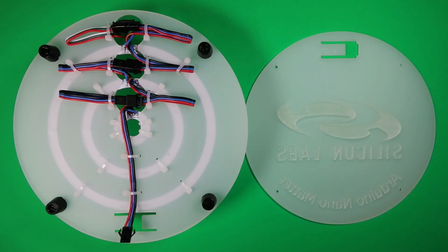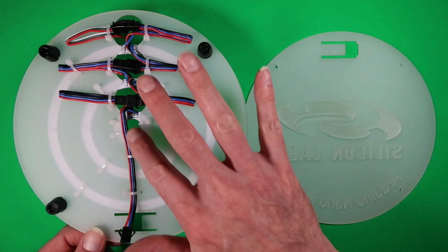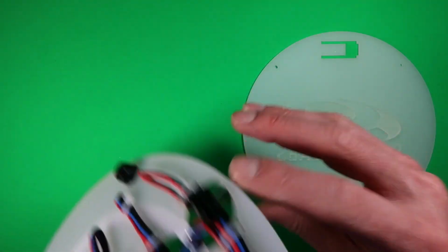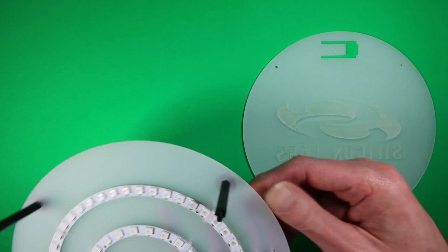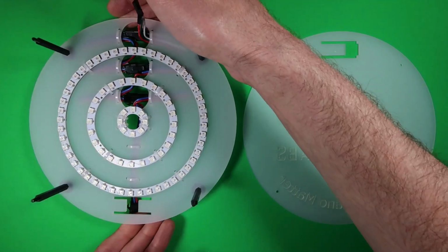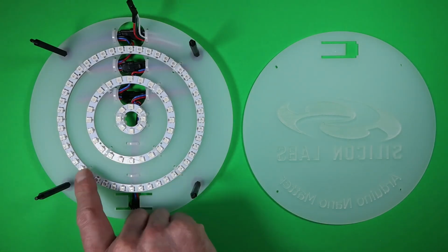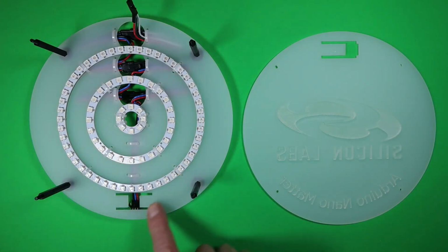To build the custom enclosure, I've used 2 sheets of 3mm opal frost acrylic, cut and etched using a laser cutter. Holes allow the wiring to be cable tied to the rear of the bottom panel, and M3 standoffs attached through rubber feet. On the front of the bottom panel, the LED rings are also attached using cable ties, and slots for mounting the nanoboard in a hidden way are also available.